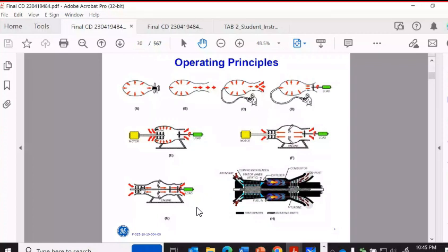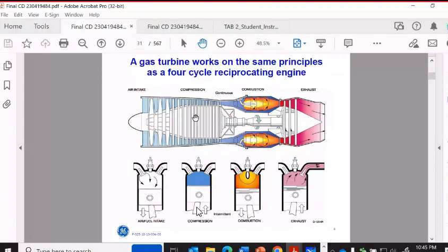And this is where, when we're talking about the turbine cycle as compared to a reciprocating type engine, we're doing all 4 cycles through here. But this was the only working cycle in a reciprocating type engine, whereas in a turbine, I can make one revolution, one complete rotation of the rotor, and I've done all 4 steps. So this is when they talk about the efficiency of a gas turbine. It's because I'm doing everything with one complete revolution of the turbine.